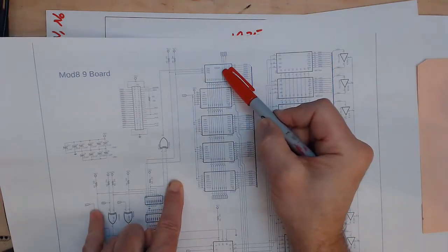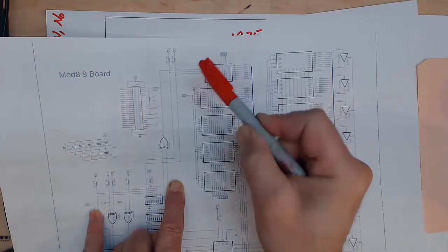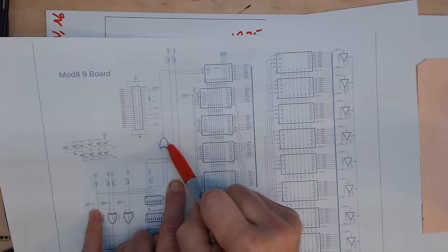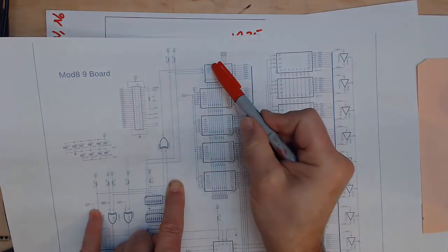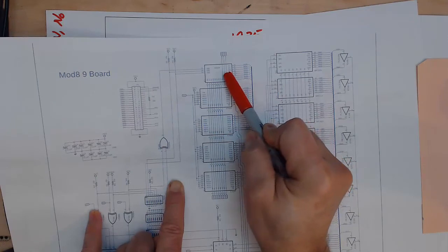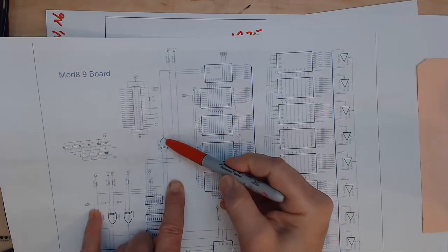So this is going low, but the problem is we may have gotten a version of this 8316 that doesn't want chip select 1 to be low to be enabled. So we have to be able to, on the fly, or using this dip switch, invert that. So this goes low, but if the number on the top said that it was 1, or 3, or anything else that ends in a 1, then this guy has to be operated in an invert mode.